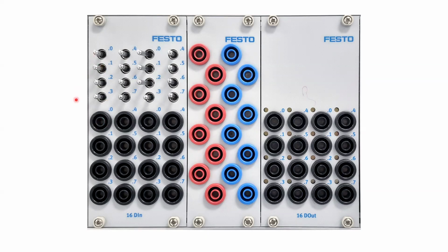Flipping this switch is going to provide 24 volts onto this. It's just like connecting a wire from the positive terminal of the power supply to that. You can do it either way. You can either do it with the switch, if you want to quickly check the logic, if you have done the program right. And then you can connect the rest of it. You can connect the limit switch, you can connect the sensor, you can connect whatever push button.